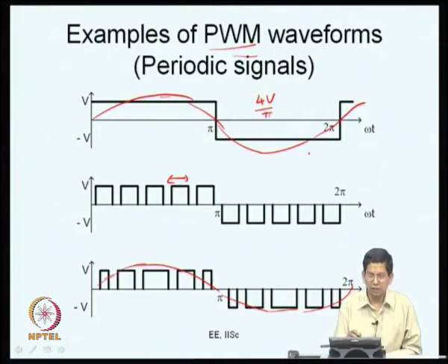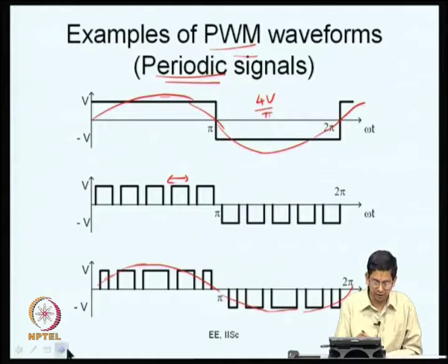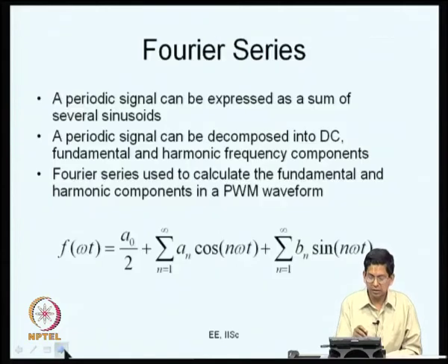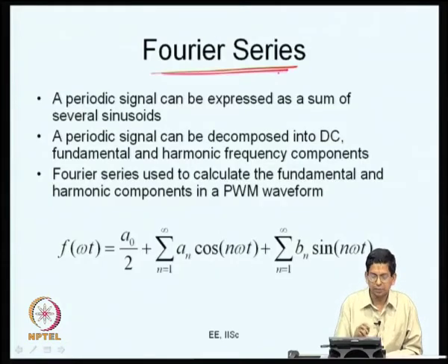All the signals that we see are essentially periodic signals. So we want to understand how much is the fundamental voltage quantitatively and how much are the harmonics, what are the various harmonics, how do we do that? Being periodic signals, they can be expanded into a Fourier series.